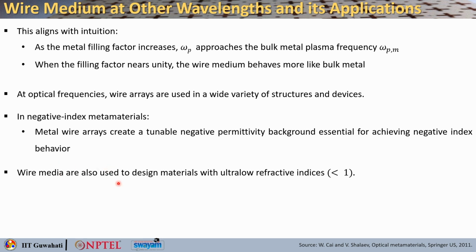Now, this wire media are also used to design materials with ultra low refractive index, which is less than 1, okay, and this could occur at frequencies just above the effective plasma frequency. So, you get a lot of tuning parameters to this effective plasma frequency, because it purely depends on your physical design of the wire and the array.